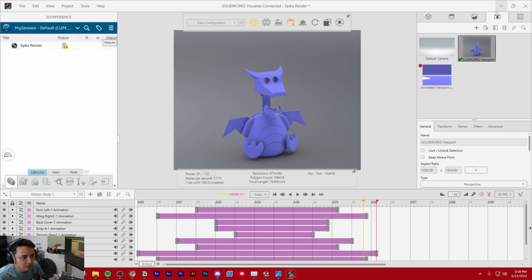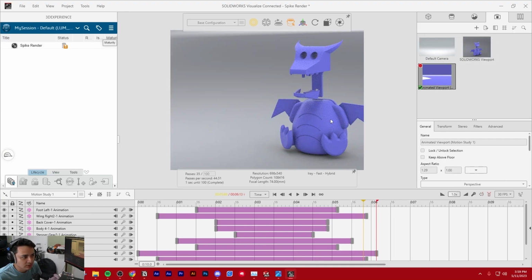Oh, and then you got to go to camera and then make sure that, so it imports your keyframes, which is great, but for whatever reason, the camera that we animated when we swung from the left front side to the right front side isn't checked by default. So make sure you go to the camera and then double click this and make sure then this will get checked. And then what happens if we play it now?